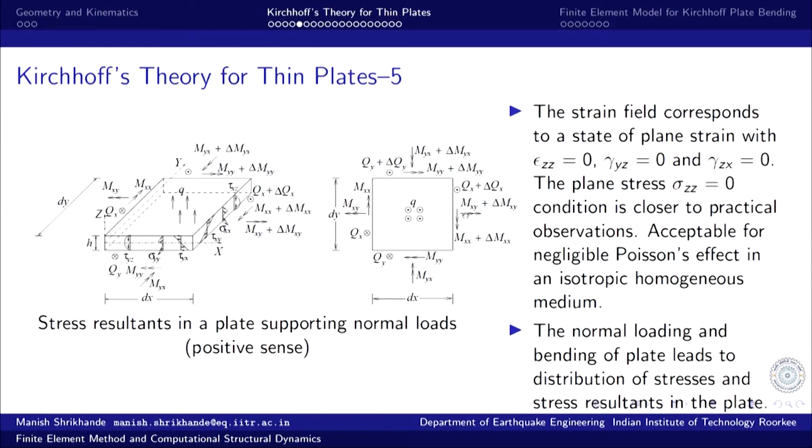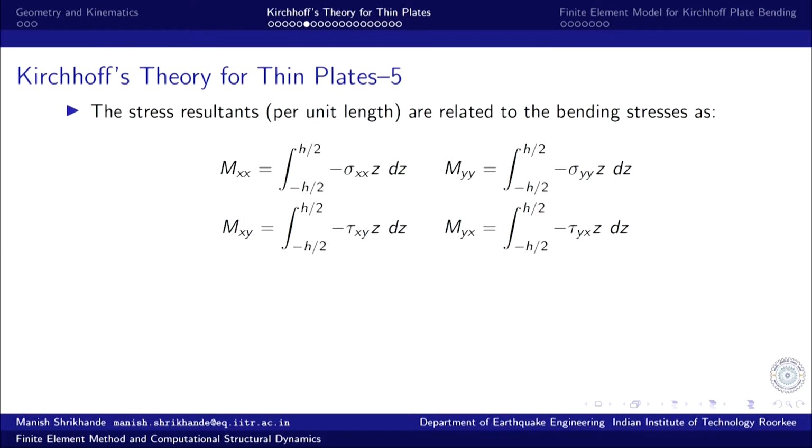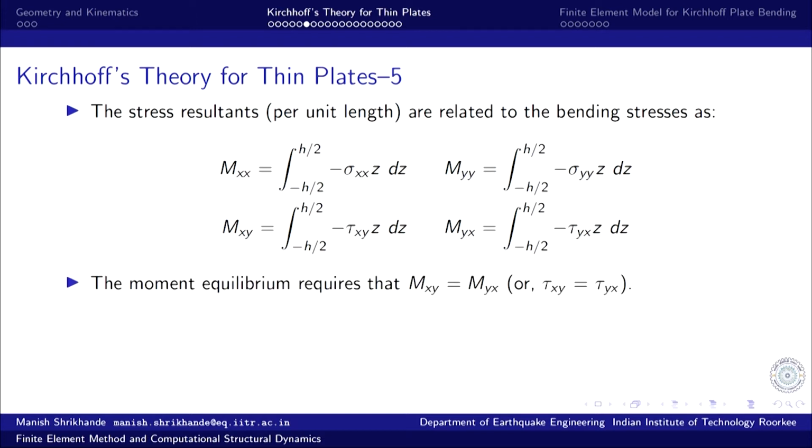So, the bending moments, these moments, are related to the stresses here, the respective stress components. So, these are the stresses and these are the stress resultants that we have. Bending moments, stress resultants per unit length, are obtained from the integration of the stress field with lever arm z, integrating over the thickness, and we get the mxx and myy, and then twisting mxy and myx.